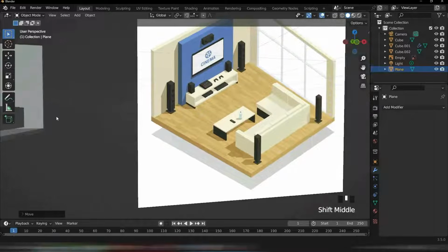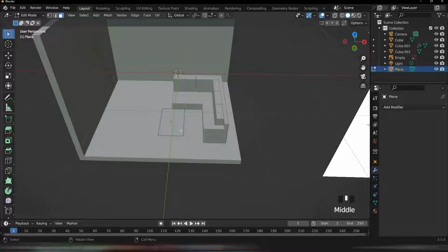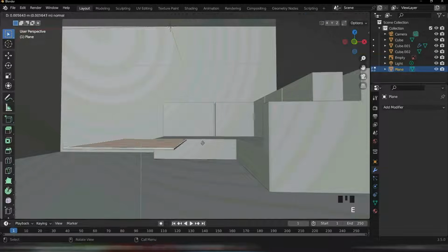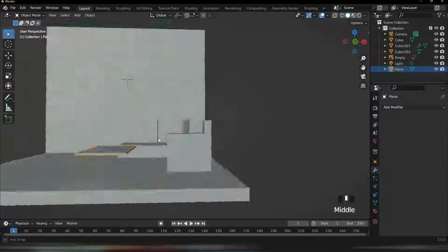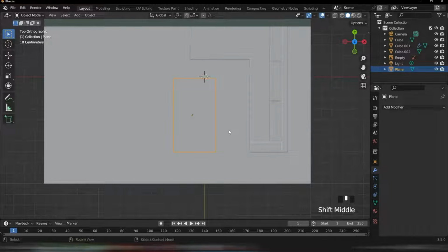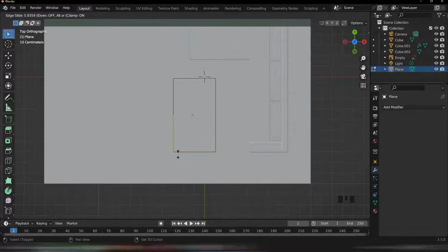Alright, now if you want, you can extrude it. Edit mode, face selection. We select the face on the top, and let's just extrude it slightly. So extrude, and you can hold shift to make it pretty thin to about there. And now we add the legs. That should be pretty simple. Just press 7, Control, go back into edit mode on this, Control R, and make it pretty thin to about there. Control R again, and let's add one right here.